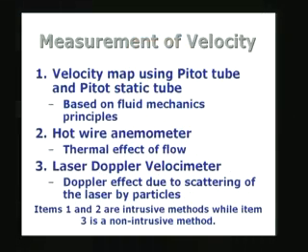velocity measurement technique, which is known as the hot wire anemometer, I am going to send a current through an element and keep the temperature of that element constant or allow it to vary. There are two different ways of working with it. The basic principle is that the amount of heat that can be dissipated from the element depends on the flow velocity. If the flow velocity increases, we know from our heat transfer studies that the heat transfer coefficient is going